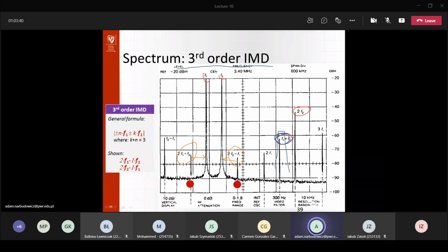Because of course, with the classical analysis of just a single frequency, you won't be able to see that. So when you're looking for intermodulation products in your system, you always need to use a dual tone excitation, and then look at the signal level at all the combinations of interest.